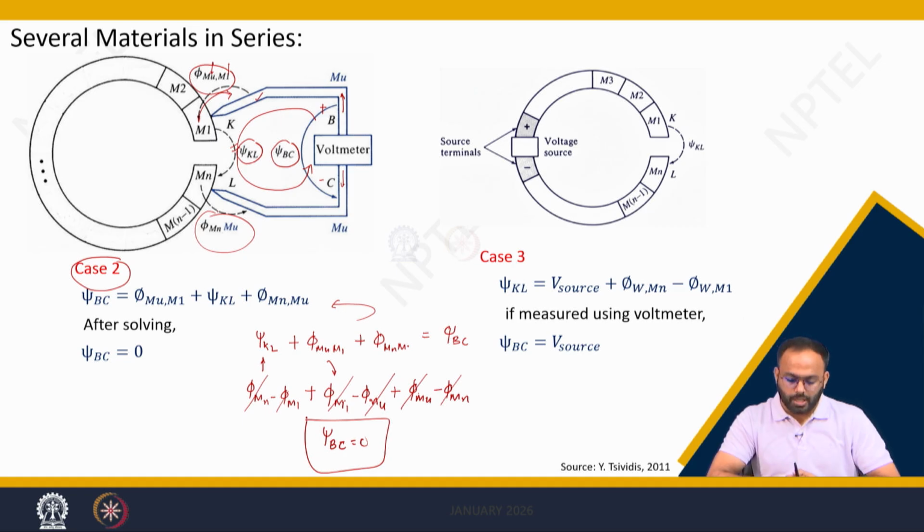You cannot measure the contact potential by a voltmeter, because the voltmeter leads make a contact potential again with the materials, right. So, this is the case we have seen in the PN junction diode also. In a PN junction diode, if someone asks, can you measure the built-in potential between P and N by a voltmeter? The answer is no, because whatever the potential difference, the built-in potential, which is psi Bi, comes into the picture.